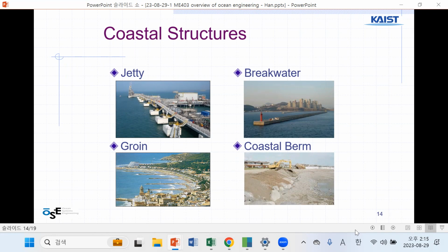Then they need sufficient water depth. Because for that kind of ship, the height can be 50 meters. 400 long, the height is 50 meters, and if half of it is submerged, then you need a 25 meter water depth.